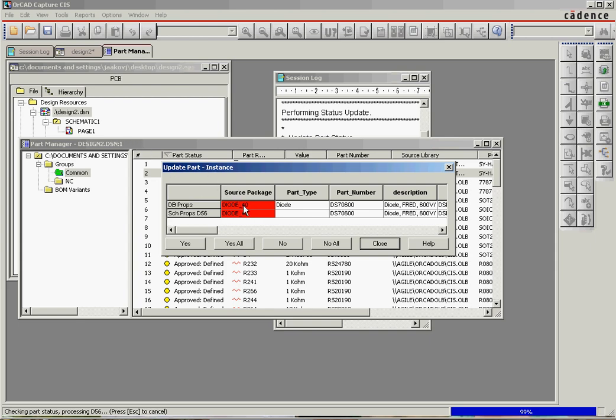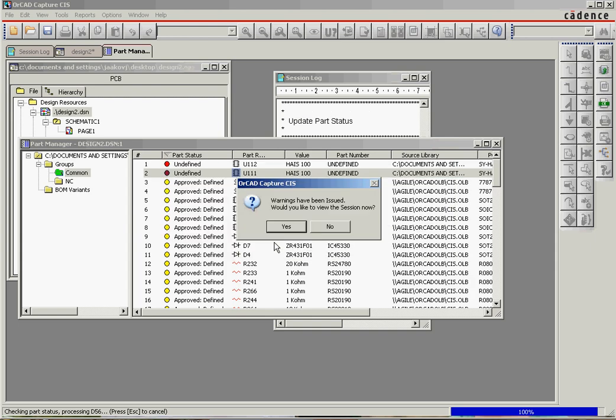The difference might only be checksum, meaning we just opened the symbol in our design and somehow edited it without any changes. Just open it for edit and save. We can click yes or no. The symbol will not be replaced in the design, whatever we click.